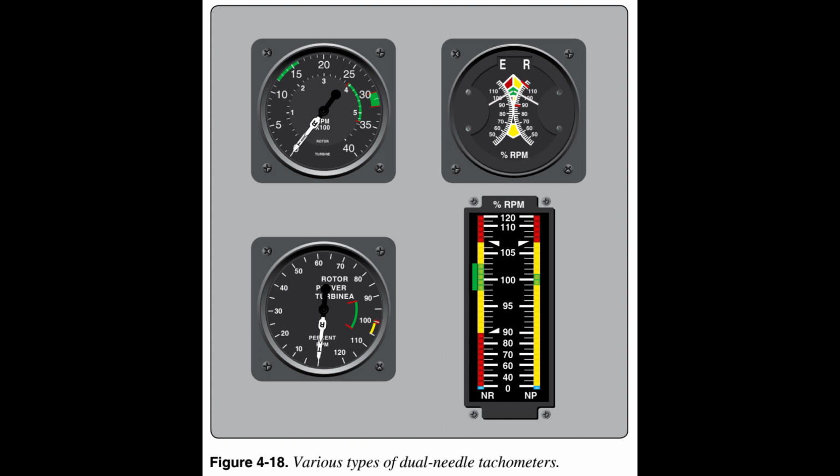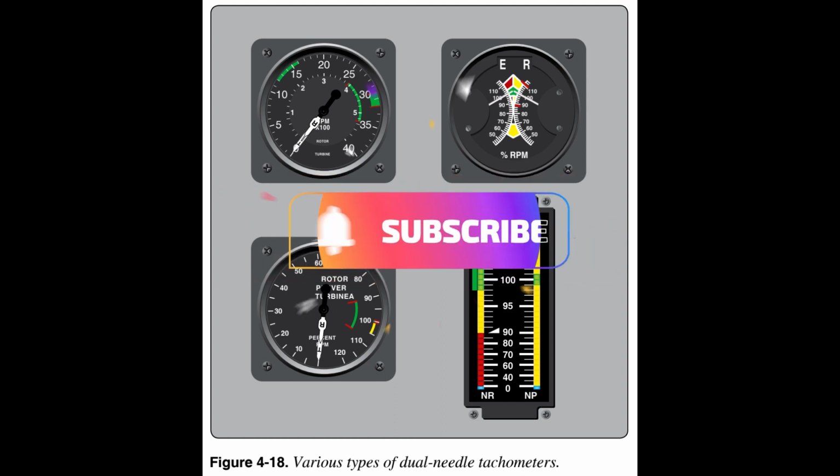Look closer at the markings on the gauges in Figure 4.18. All gauges shown are dual tachometer gauges. The two on the left have two needles each, one marked with the letter T, turbine, the other marked with the letter R, rotor. The lower left gauge shows two arced areas within the same needle location. In this case, both needles should be nearly together or superimposed during normal operation.